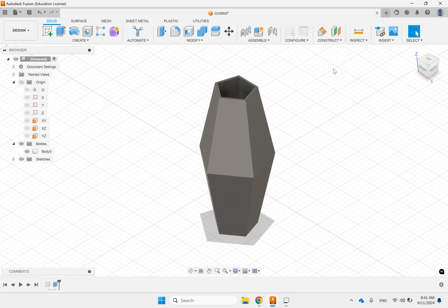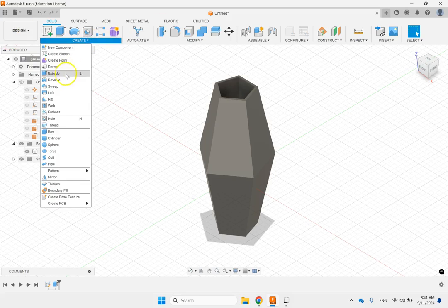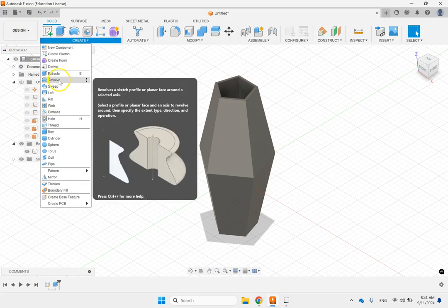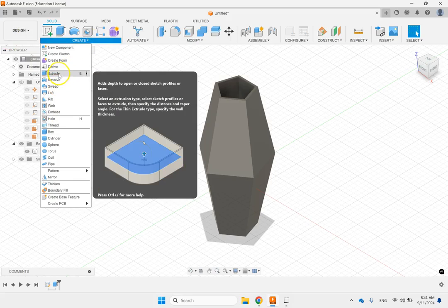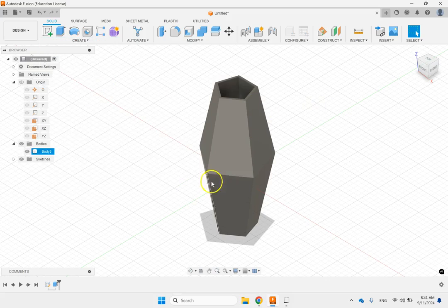Now you might say, well, where's the Cut-Extrude? I did not see any Cut-Extrude here, right? Because if you go here, you do not see any Cut-Extrude or Cut-Revolve or Cut-Sweep. Well, the thing is, inside the extrude, you have the option to make it Cut-Extrude. Where is that? Let me show you. Let's say, for instance, I want to make a circular hole through this object. On one side goes to the other side, right? Or something like that. So for instance, just on one of the faces.